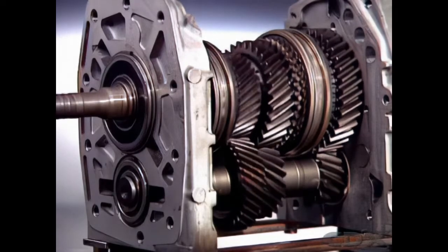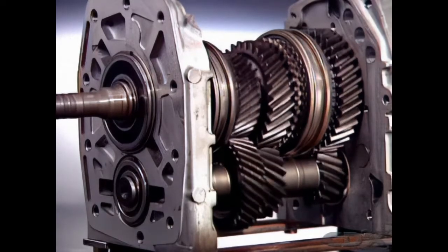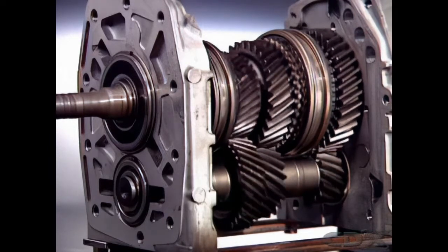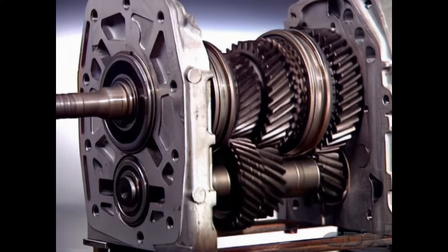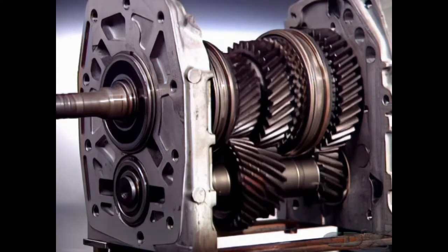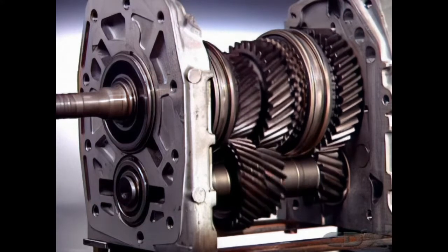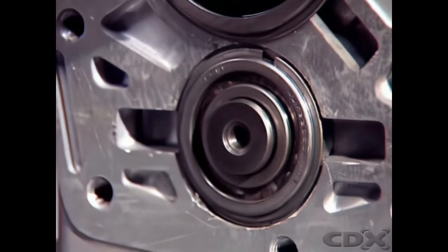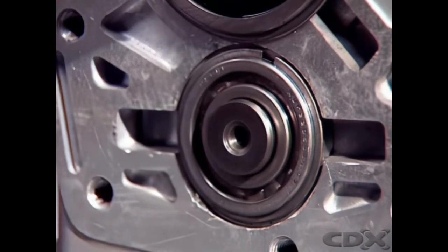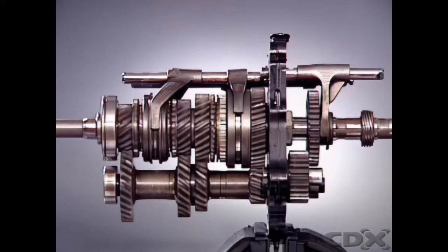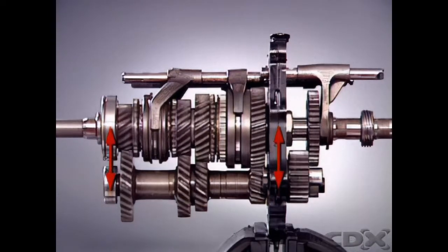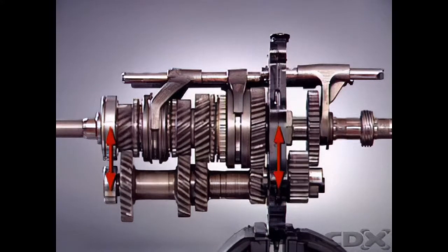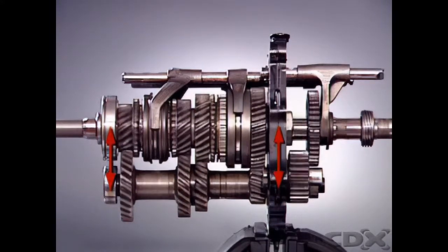In a manual transmission, the gears and shafts are supported on bearings or bearing surfaces. This allows for rotation and also maintains the alignment of the components. The type of bearing used at each locating point depends on the load which must be sustained. Radial loads try to force the gears and shafts apart. The bearing, therefore, carries the load along its radius.